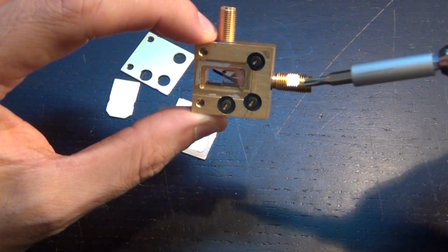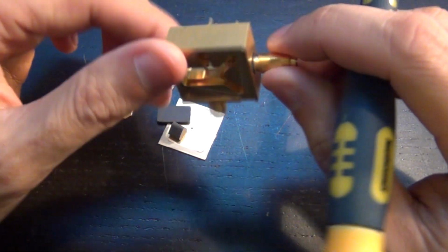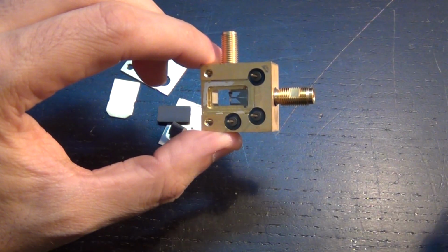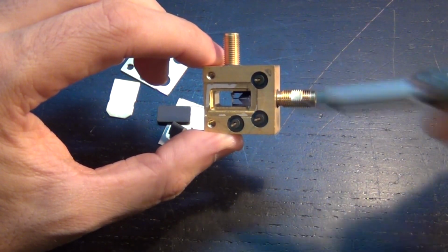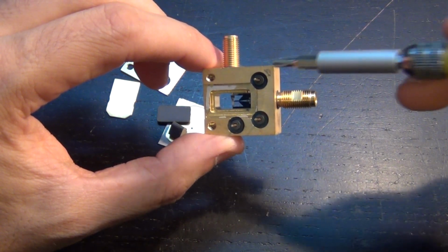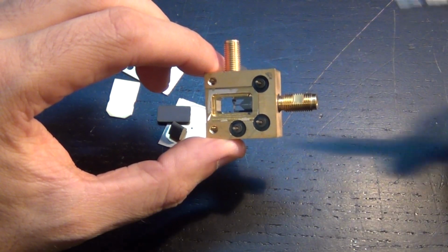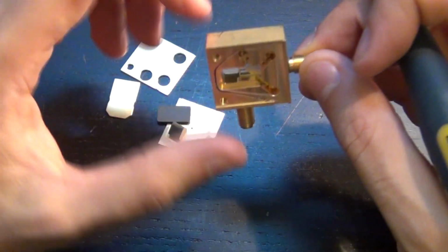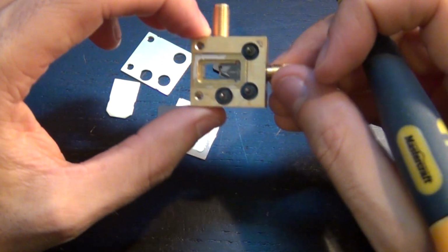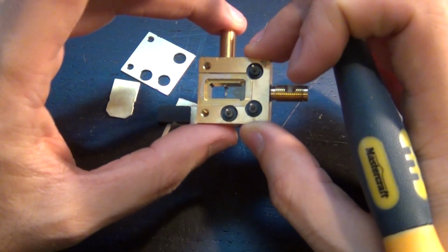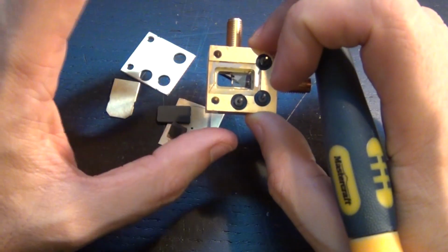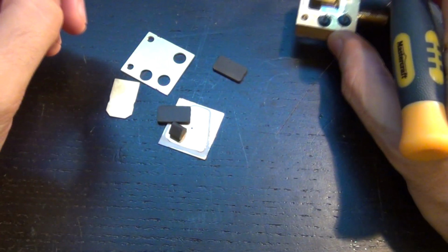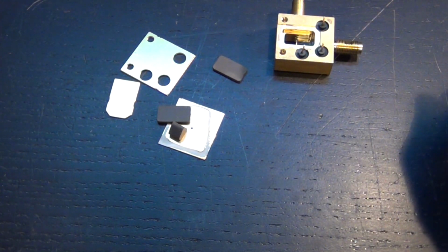The input being on this side, if I'm not mistaken, I forget now, I should have marked which one was the input, but either way, one of them is the impulse train, one of them is the input coming in, and then these guys are used for biasing, and of course the IF signal coming out. And the IF signal going through this will go through the PCB and then onto the board that I just showed you, the low noise IF amplifiers. That's how the interface is made. Totally custom, just for this purpose. Pretty amazing. It's similar to what I showed in one of the other videos for the frequency counter that had a step recovery diode built into the same module. But this is just the sampler, no step recovery in this one.